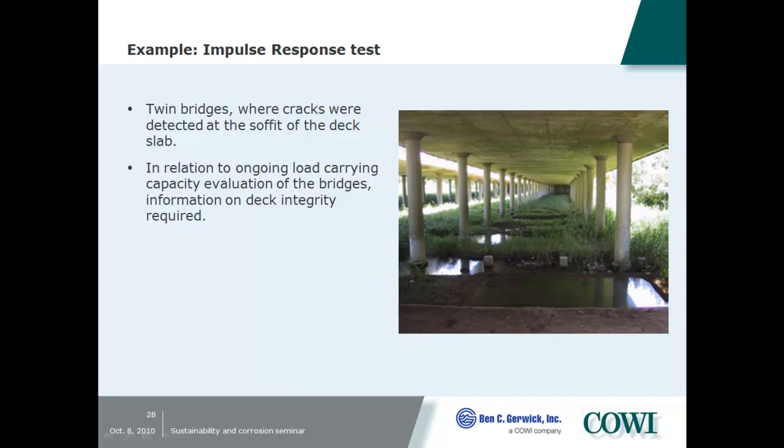So do you use one geophone, or an array of geophones? One geophone: hammer tapping, move to the next area, hammer tapping, and pick up signals. So then the signal that you get would only be at that geophone location? Yes. Do you also consider the path between the hammer and the geophone? They are normally just closely next to each other, as close as practically possible.